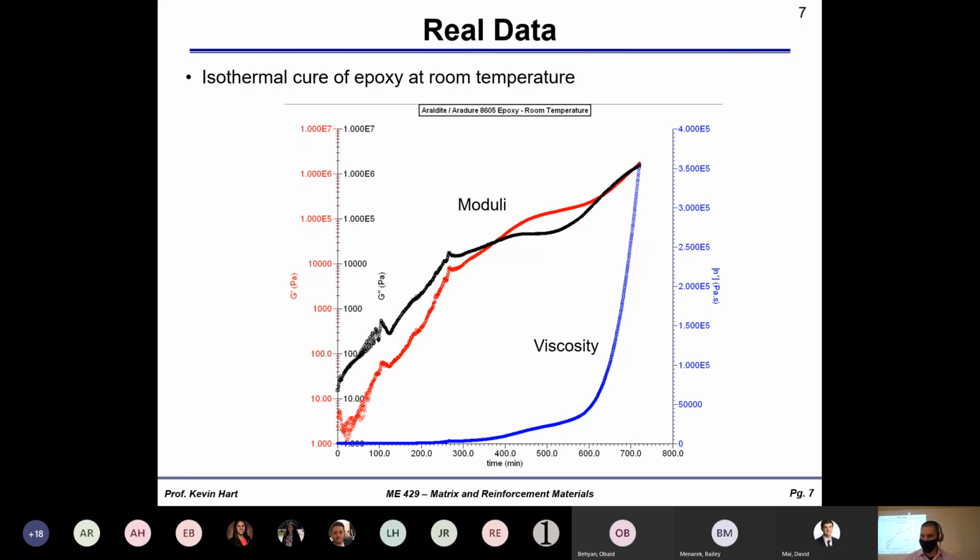So we see this particular resin at time t0. It starts with a viscosity of more or less 0, so think water-like or very similar to water. And then over time, it becomes more and more and more viscous. I'd say here at about the 400-minute mark, we're probably approaching a point of no return, where we're probably not going to be able to manufacture much anymore after this. Viscosity rising, and then right at about the 600-minute mark, this thing really just takes off. So I'd say you could probably get away with maybe 360 minutes of working time for this resin. It's maybe 6 hours is probably appropriate. And you're probably fully solidified at 12 hours, right?